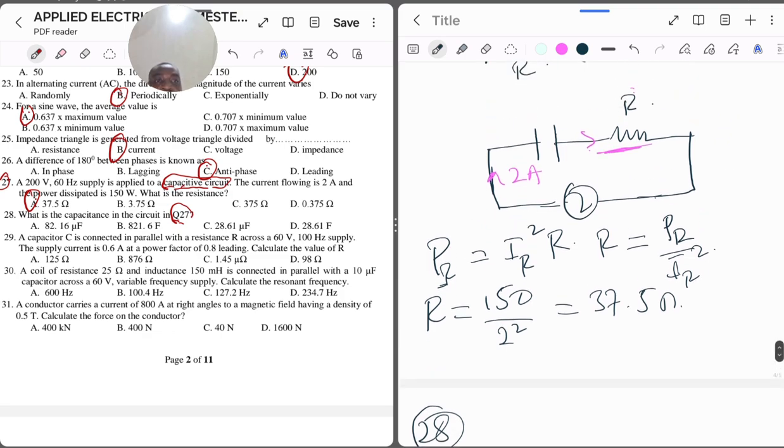The capacitor, which is C. I'm using C to represent the capacitance, which is what we are interested in finding. Now, if you look at this very well, you can see the same current is passing through the capacitor and the resistor, because they are in series.